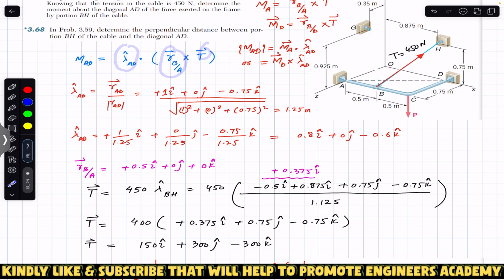So we will find the unit vector from A to D. Now the unit vector from A to D is the position vector from A to D divided by its magnitude. Now the position vector from A to D is this vector. So we must find this position vector from A to D. In order to write it, we must start from A and try to reach that point D while traveling along the X, Y, and Z.